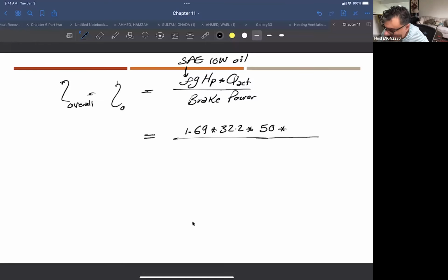Gallons per minute is not the basic unit in the British system, which uses cubic feet per second, so I have to convert the 117.4 by dividing by 449. This gives you everything in feet, seconds, and pounds.